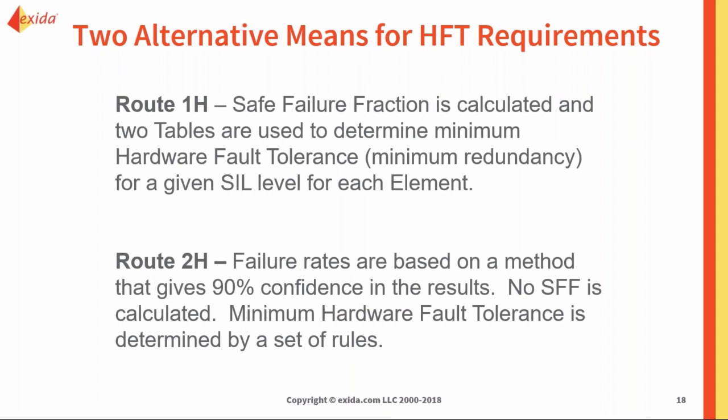So when we're doing that FMEDA process, we also go through each individual component and see if it meets the requirements for 2H. If every single component in the device meets that proven in use or prior use justification requirement, then the entire product is 2H qualified. So we have a massive database of all these components that we've been collecting for over 20 years to analyze the history of each of those components in that exact environment.